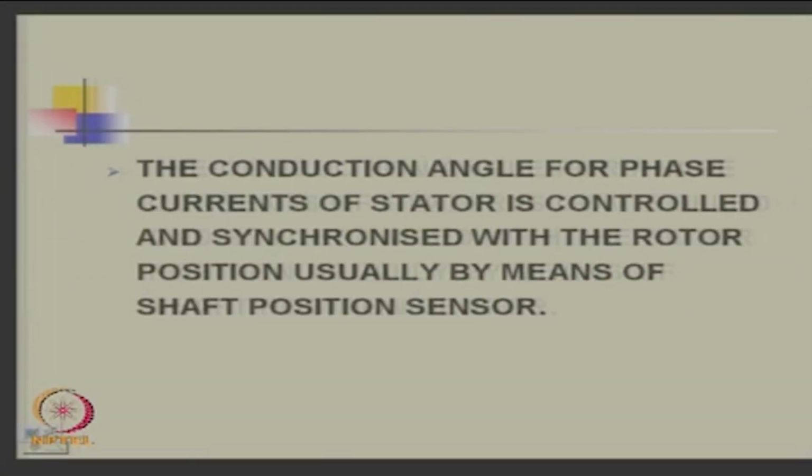So, conduction angle for phase currents of stator is controlled and synchronized with the rotor position, usually by means of a shaft position sensor. Okay. You sense the position and do this. So, you do some signal processing. Nowadays there are tools available for you.